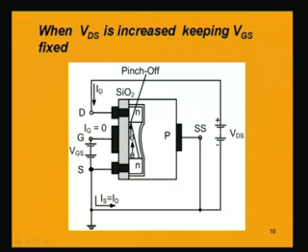This width will be maximum at the source, and if we go up, the channel width will be reducing, tapering towards the drain, because the width of the channel depends upon the available voltage between the gate and the drain. Because if the gate to drain voltage goes on reducing, then the attractive force which it exerts upon the electrons will be reducing.